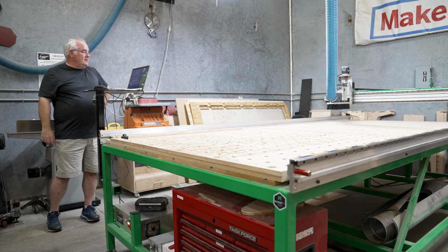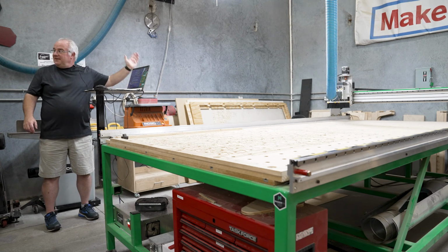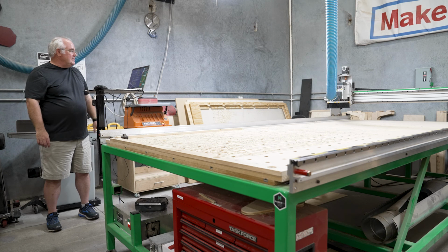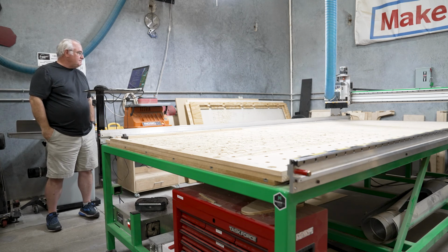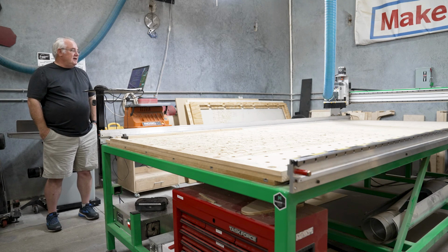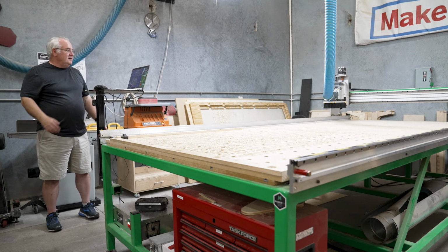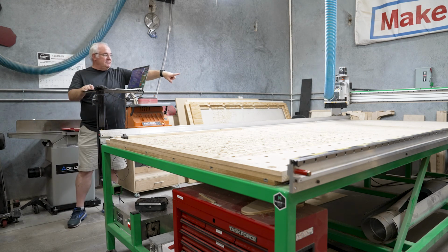The machine's now running through a job that is going to move. It starts with Z. You hear that click? That's where it moved up and hit Z. And it's now doing the same thing for the X-axis. You can see the spindle starting to move over, and it's going to hit the end stop. And there are 2 end stops on the side of the gantry. This is going to take the longest part of this, moving that X end. So it's moving very slowly. You can see one of the end stops over there on the right.